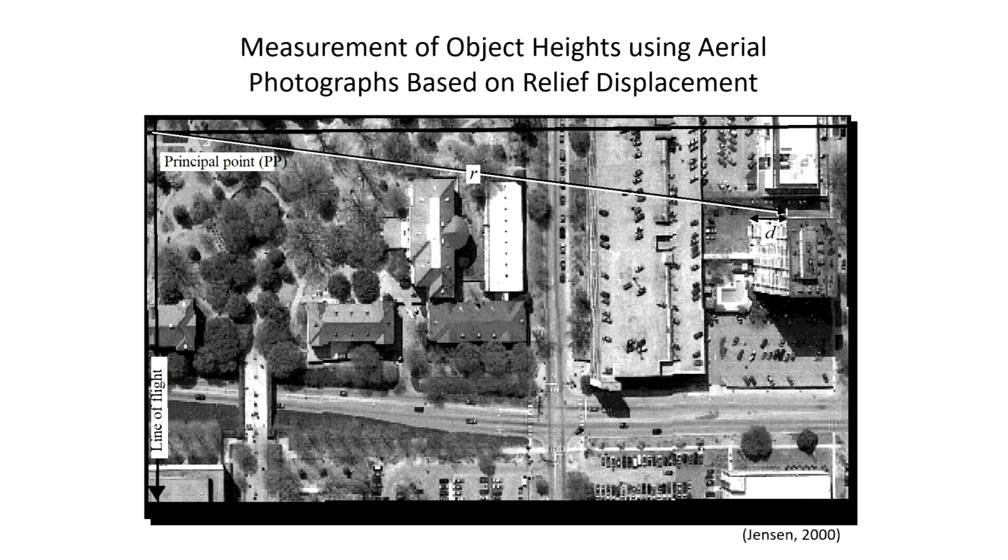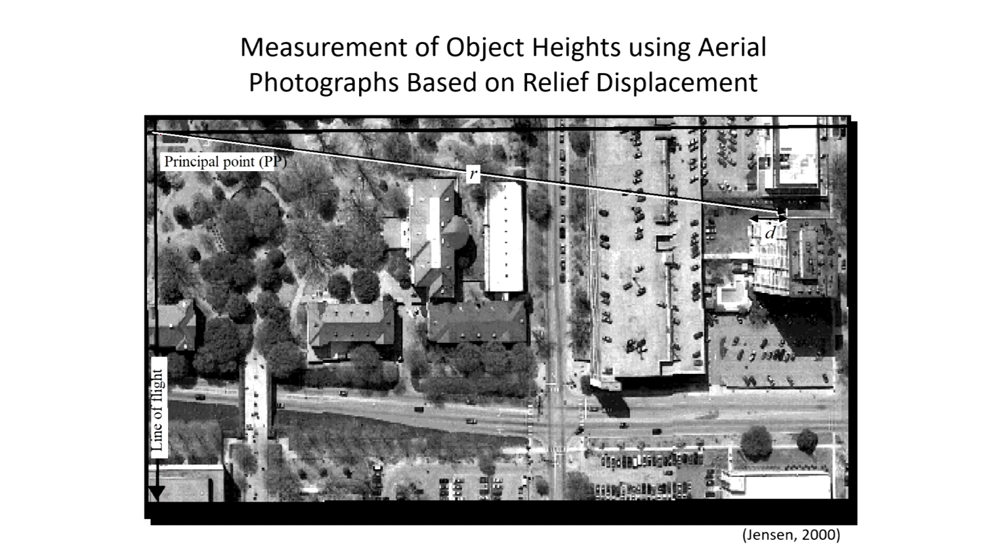Now, the best way is to use the principal point on the photograph. Considering the photograph has been taken vertically, this will also be your nadir point.